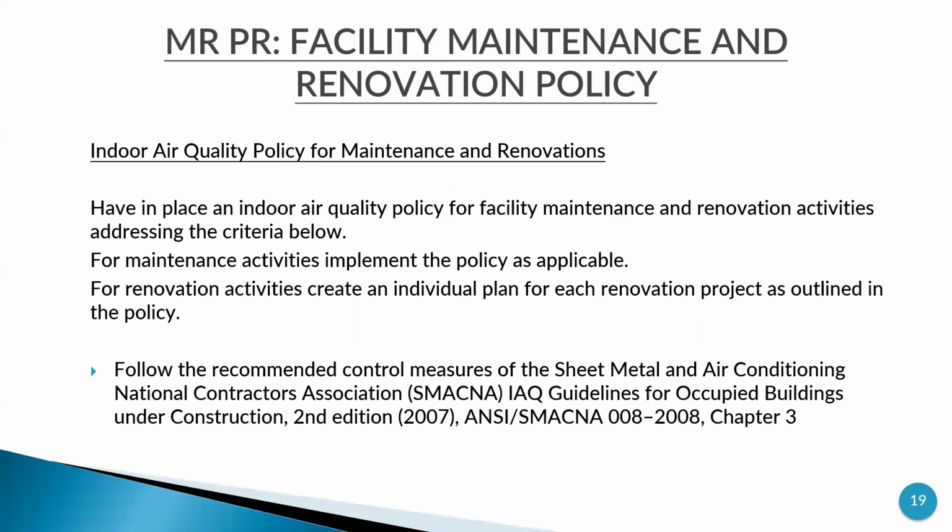Now, indoor air quality policy. Have in place an indoor air quality policy for FM and renovation activities. For maintenance activities, implement the policy; for renovation activities, create an individual plan for each renovation project as outlined. Here, when you talk about indoor air quality, we are talking about the recommended control measures from the Sheet Metal and Air Conditioning Contractors National Association, SMACNA we call it.